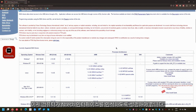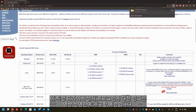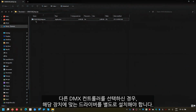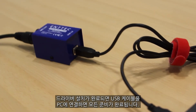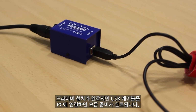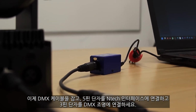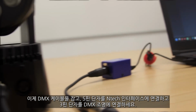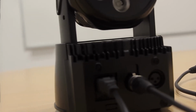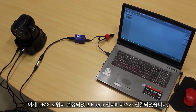Now we need to make sure your computer will recognize the N-Tech interface. We'll provide a link to this particular driver installer in the video description. If you choose a different DMX controller, you'll have to get your own driver. Once that's installed, you can plug the USB cable into your PC and you're all set. Now grab the DMX cable and connect the 5-pin end to the N-Tech interface and the 3-pin end to the DMX light. You now have your DMX light configured and the N-Tech interface connected.